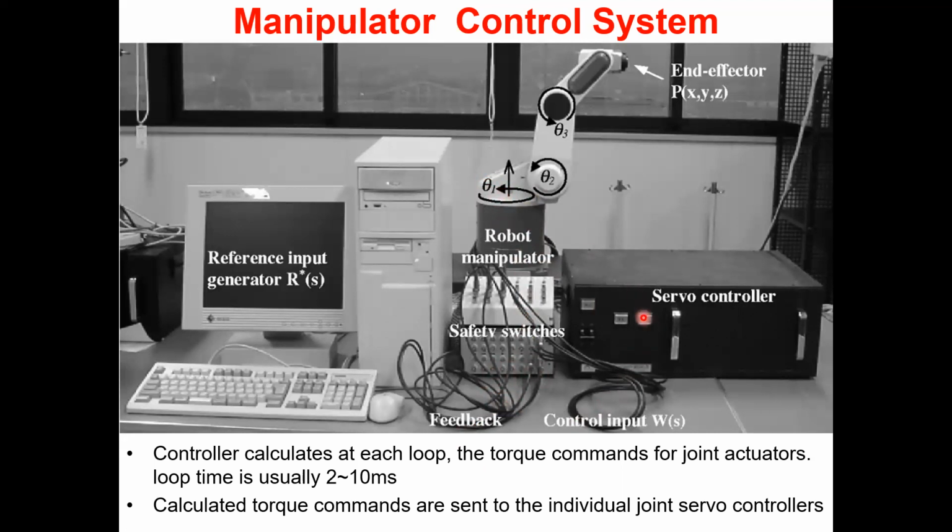Then the servo controller knows the error, the difference between reference and actual. That is the error. And there is a particular compensator, the control system, right? And it will eventually drive the servo motor in a suitable manner so that theta 1 actual angle goes to the desired angle. And it has 10 milliseconds to do that.